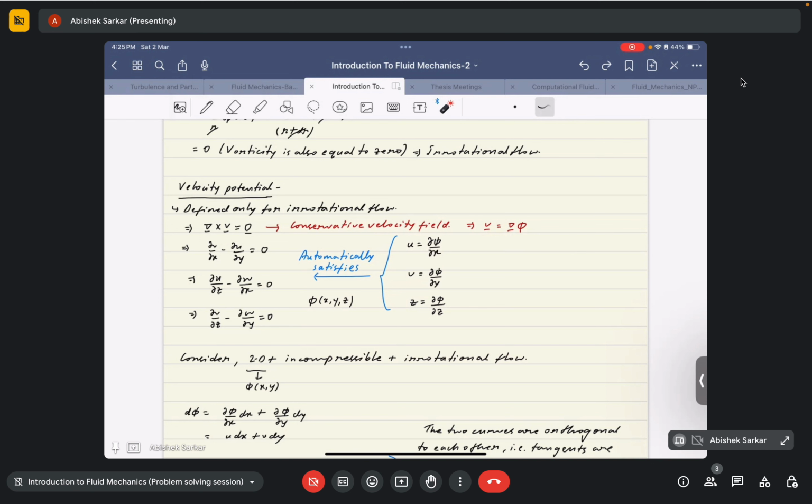So from that we use the incompressible continuity approximation and thus tell that if a flow satisfies the continuity equation, it should have a stream function, and since the flow also has to be 2D, it will only have two velocity components, and from that logic we derive the functional relation between the velocity components and the stream function.